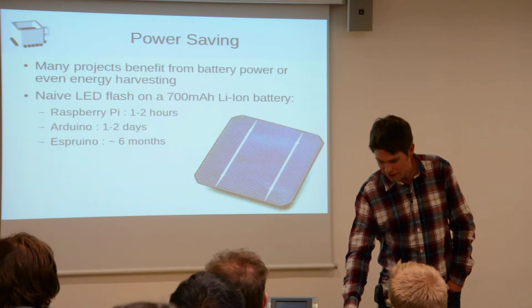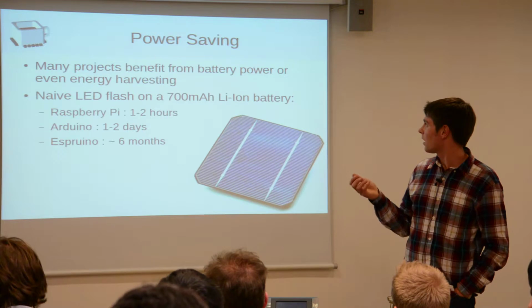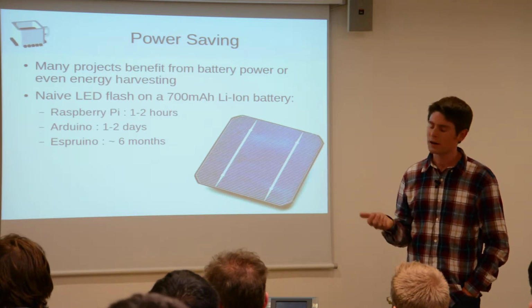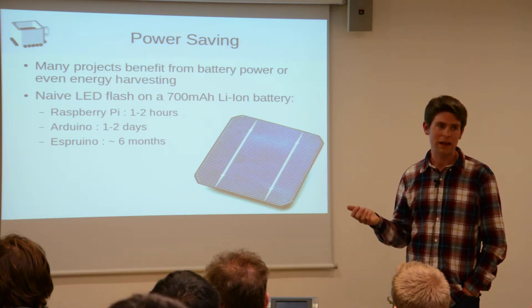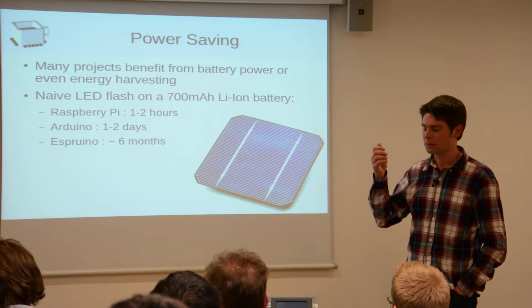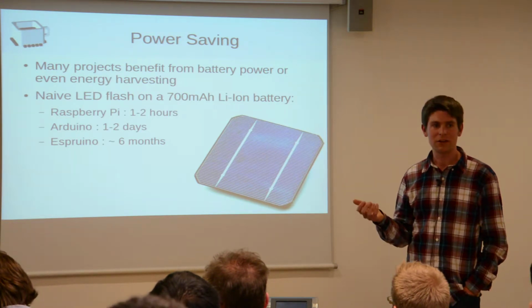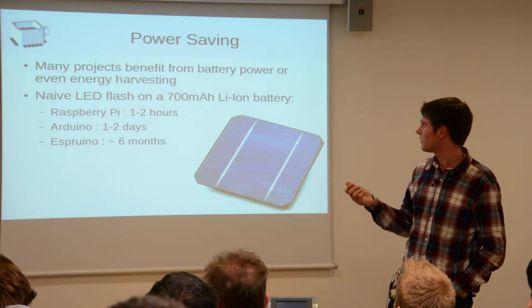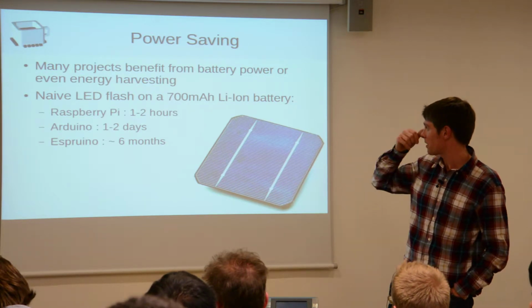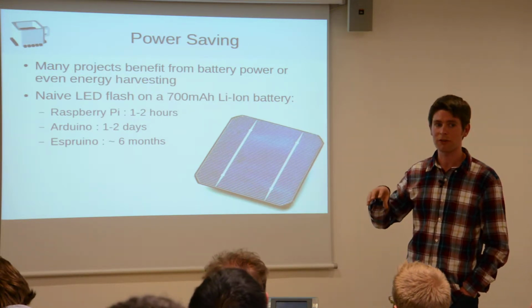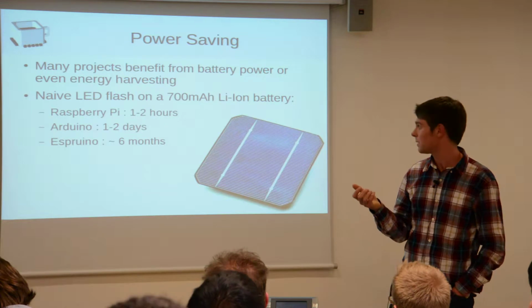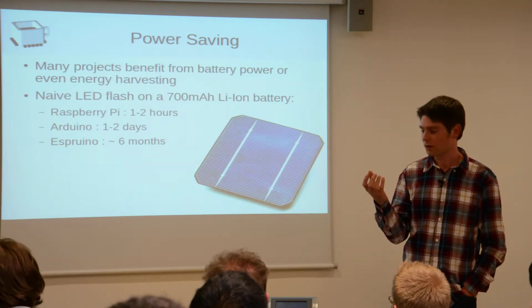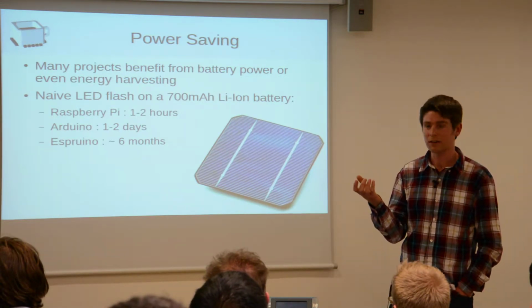So that's great. And as I've said before, I think it's a bit underserved. If you're doing some kind of data logging in your house or any handheld device, you want battery life. And Arduino doesn't really do that very much. If you look at a 700 milliamp hour lithium-ion battery, the kind of thing you'd get in a Nokia candy bar phone, a Nokia phone lasts for 30 days on that.